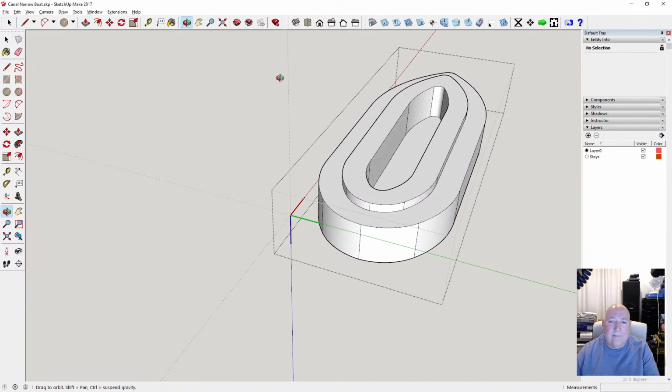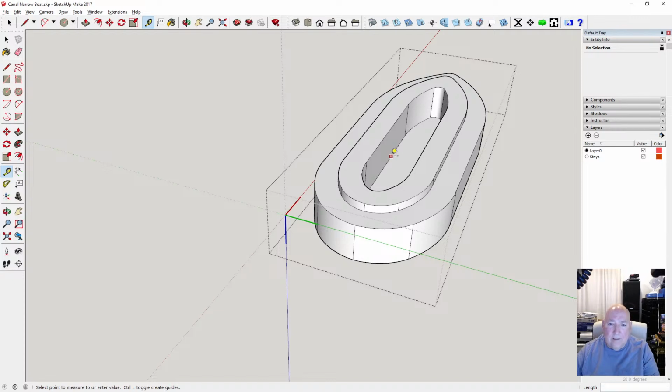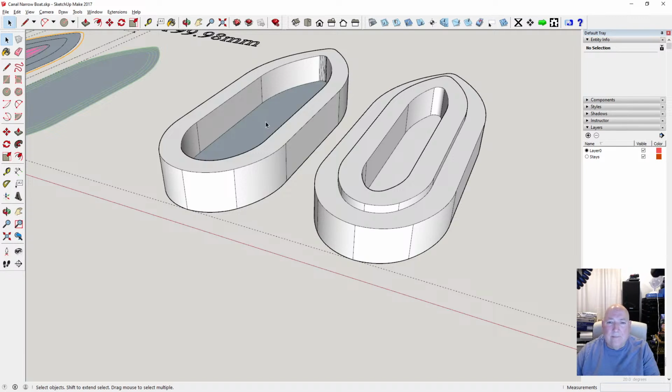Now the bottom, what thickness have we got milling out of here? 18mm. So I need to come up 1.5mm. So that leaves us depth of 16.5mm, the rim size of 3.5mm. Okay, that looks good to me.